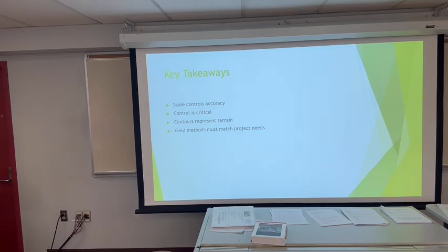Okay, key takeaways. Scale controls accuracy. Control is critical. Contours represent terrain. Field methods must match project needs. So again, if you're inside a building, you're not going to be able to use your GPS unit.